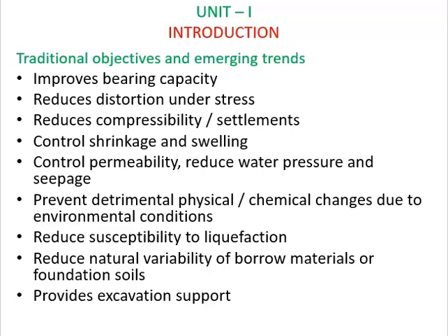Then the traditional objectives and emerging trends in the ground improvement techniques are to improve the bearing capacity or to reduce the distortion and stress, to reduce the compressibility or settlement, to control shrinkage and swelling, to control permeability, to reduce water pressure and seepage, to prevent detrimental effects due to environmental conditions, to reduce susceptibility to liquefaction, to reduce natural variability of porous materials or foundation soils, and to provide excavation support.